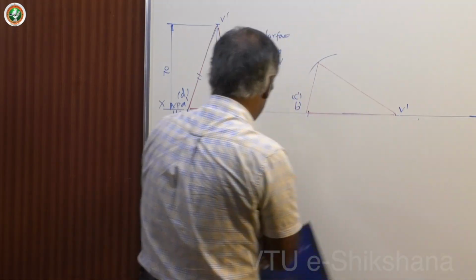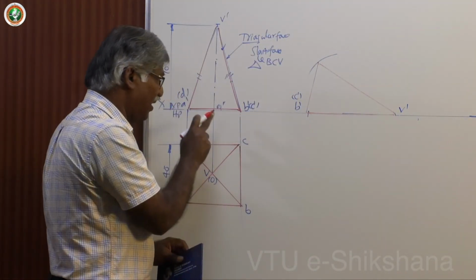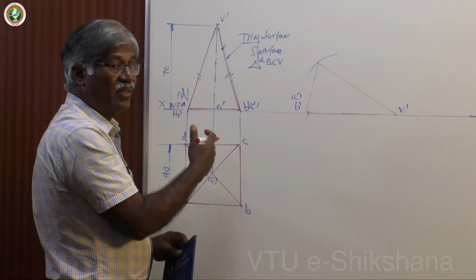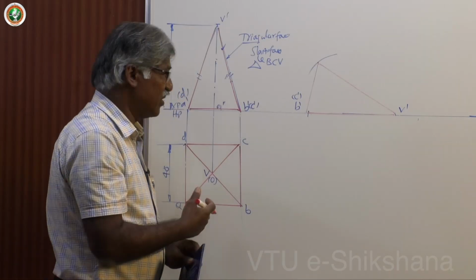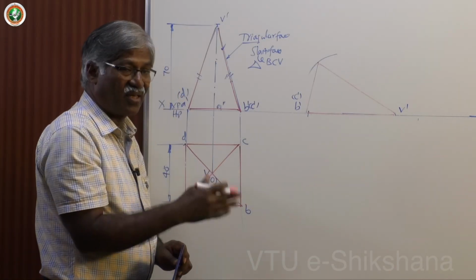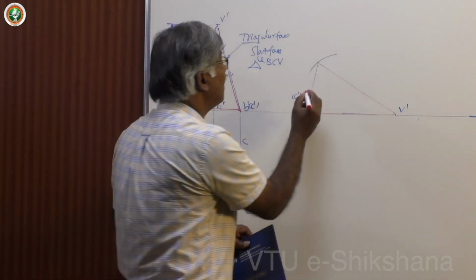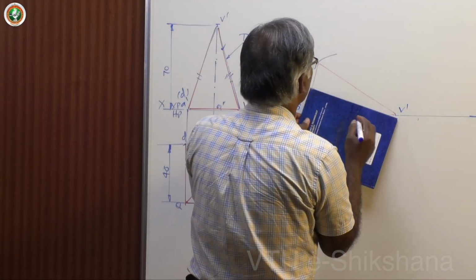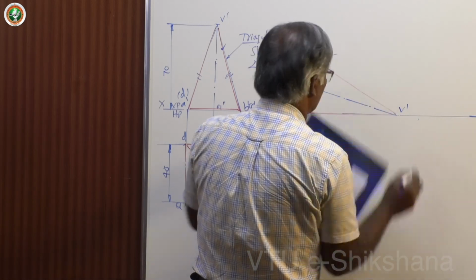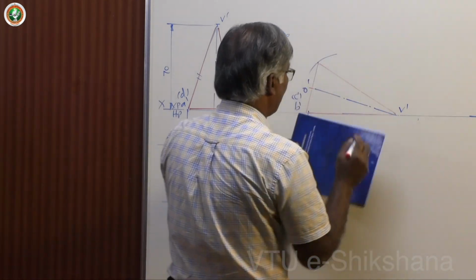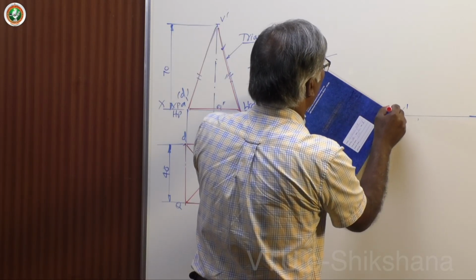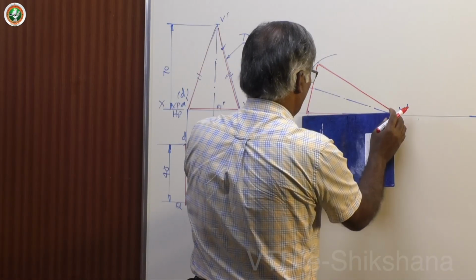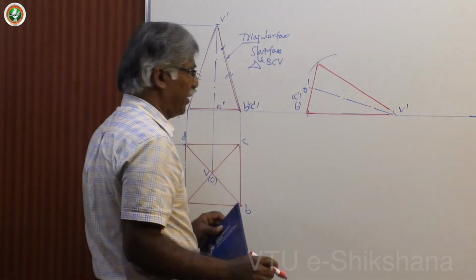Irrespective of the shape, if it is hexagon or pentagon, it is the same, but for pentagon and triangle you have to be very careful. The axis is biased towards right or left, all depending on whether the slant edge or slant face is on HP. In this case it is symmetric, as in the hexagon and square. So, easy. Now, mark the center O dash V dash. I always prefer to have V and O instead of O1. I will justify that with a particular problem in future.